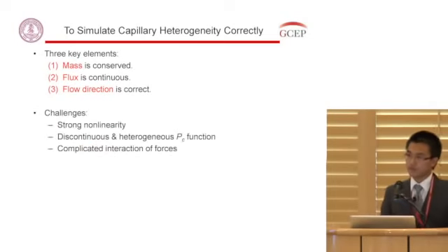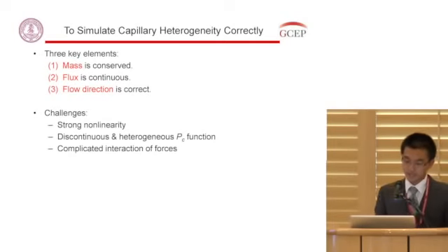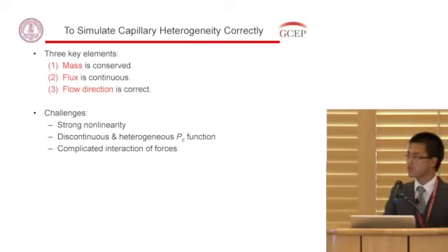But the challenge of capillary heterogeneity is such that, first, the strong nonlinearity introduced by the capillary pressure term makes it very difficult to solve the mass conservation equations efficiently. And second, the discontinuity and the heterogeneity of the capillary pressure functions pose a significant challenge in honoring flux continuity.